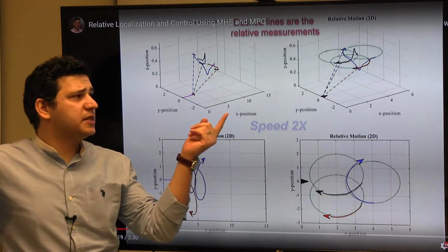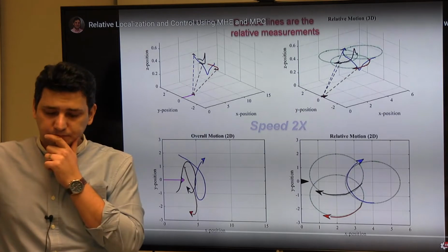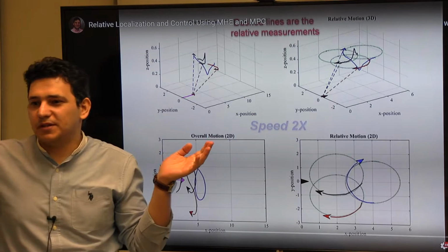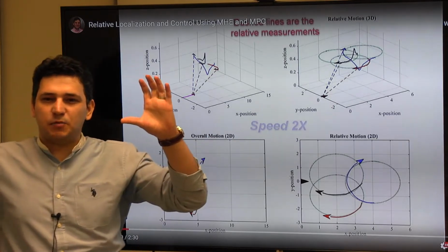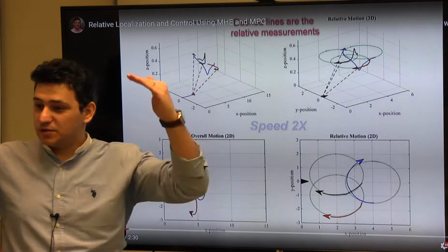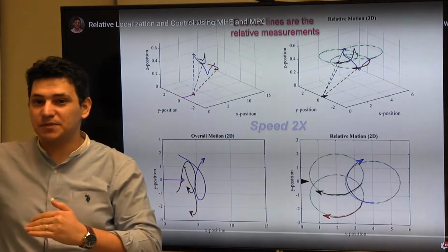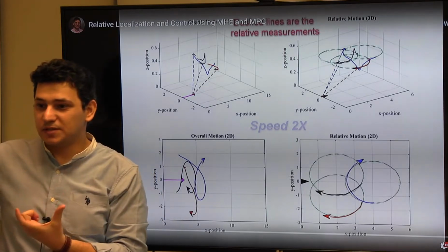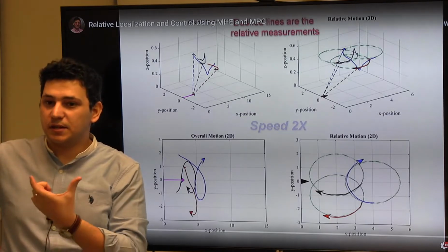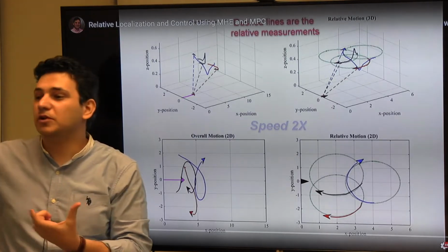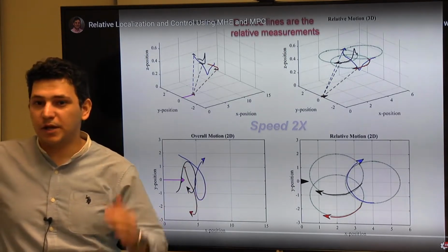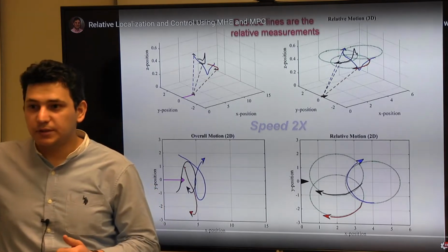And when we applied MPC here, we used centralized MPC, because here we have 3 robots apparently, right? So we ended up with a system model that has 3 times 3 states, so 9 states, and 6 control inputs. And in the constraints part of the problem formulation, we made coupling constraints between each pair of robots so that they don't collide with each other. So that's called a centralized implementation of MPC. You put everything in one optimal control problem, right?